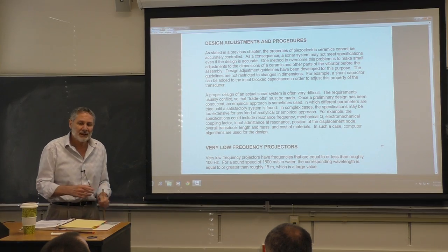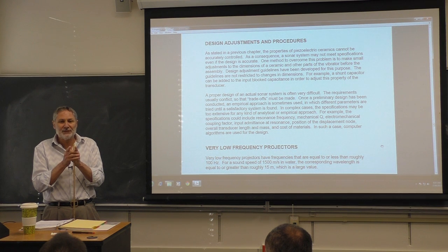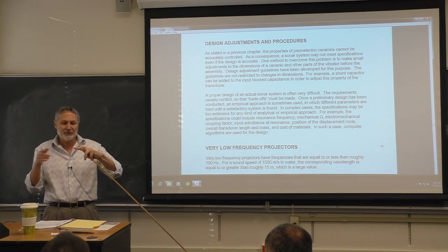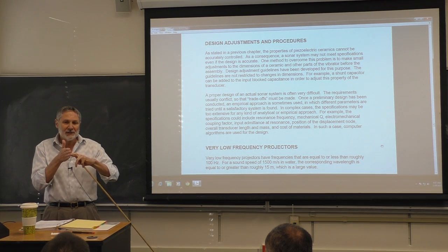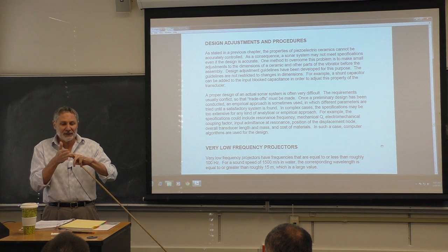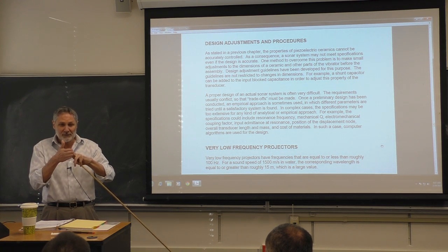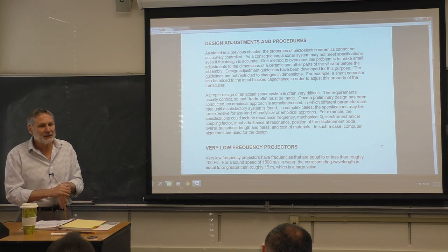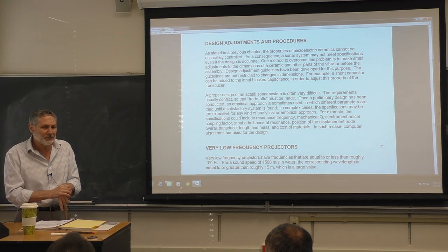So in the case of measuring the voltage difference, it's critical. It's very critical. In other words, when the sound wave is coming here and you're looking at the voltage difference from these two pressure microphones, they had better be very nearly identical because you want to pick up 0. You want to just pick up the sound wave coming in this direction. So in that case, it's critical to have identical transducers.